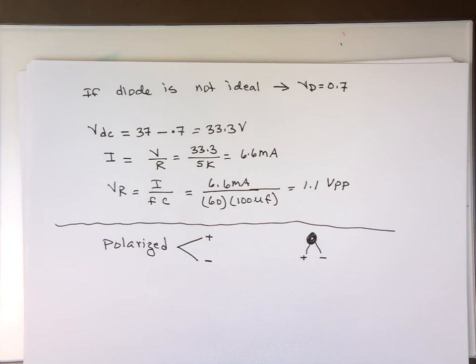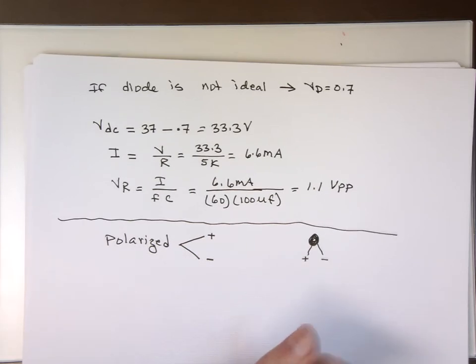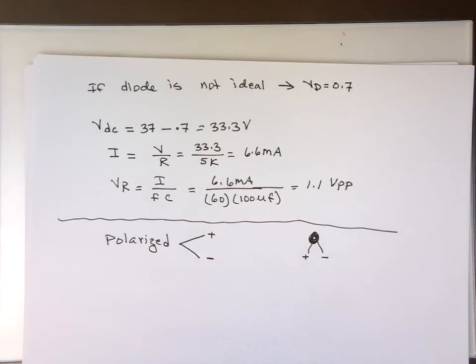If you reverse that polarity, this capacitor will get hot and may explode. So just keep an eye on that if you decide to build that in the lab and test it, if you're using polarized capacitors.